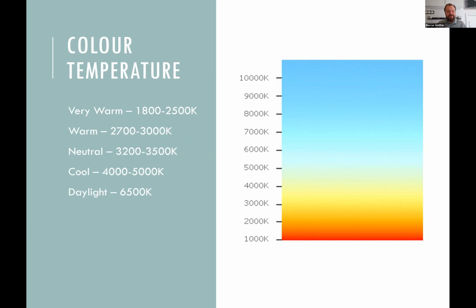And there are a whole range of very warm whites as well. If you want to create that lovely, beautiful candle glow, you could be looking at going down to 2,000 or 1,800 even, which has got a lot of amber in it, very, very warm colors. And it really has to be tailored to the project, but those are a little bit more specialist. Generally, we're looking at 2,700 to 3,000 on a project. It is very much bespoke and tailored to the project which you're looking at.